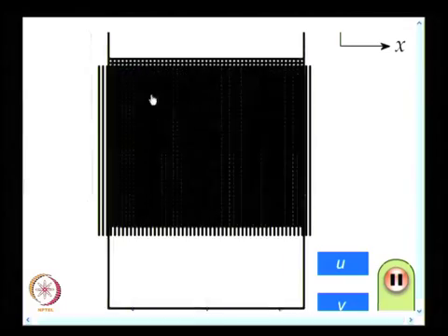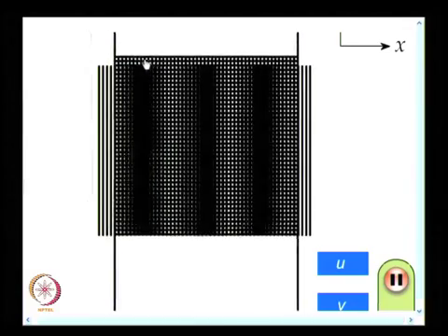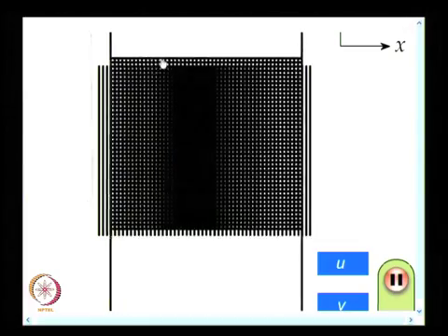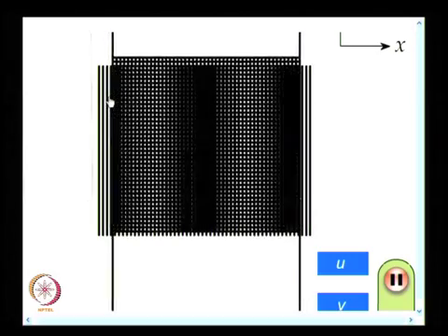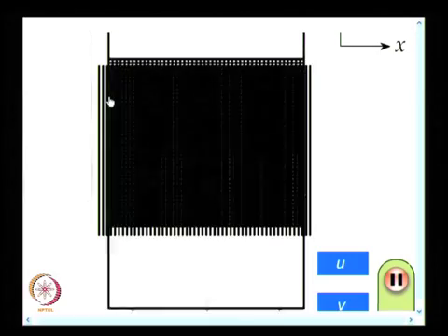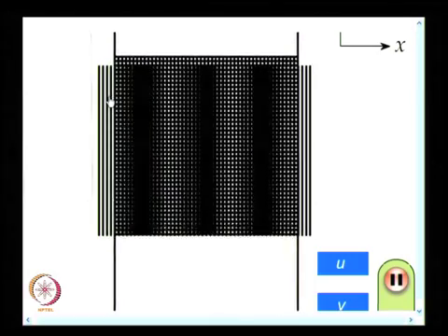So, what I have is, on the specimen I bond only one grating which has crossed lines, but I view this with a horizontal grating or a vertical grating. So, I can comfortably switch over from U displacement to V displacement. Data interpretation is not difficult, it is very important, because the next technique we are going to take up is holography.